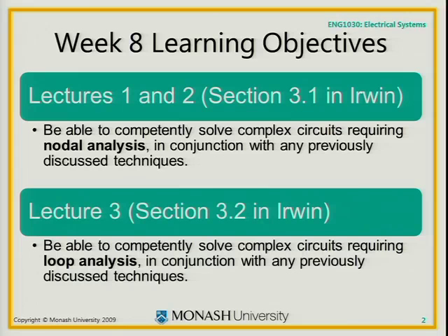So if you use Kirchhoff's current law at all the nodes, that's called nodal analysis. If you use Kirchhoff's voltage law around all the loops or meshes, it's called mesh analysis or loop analysis. And they're the techniques that we will look at this week.